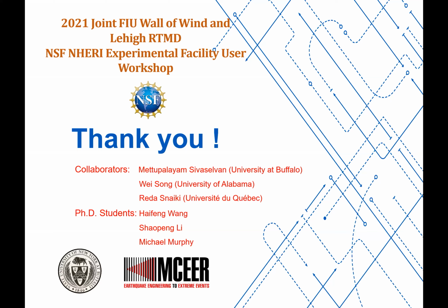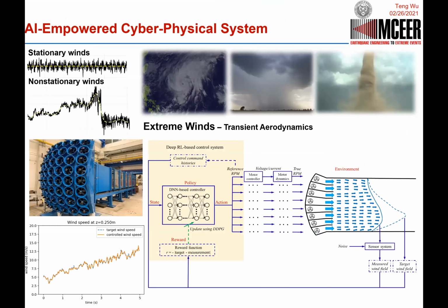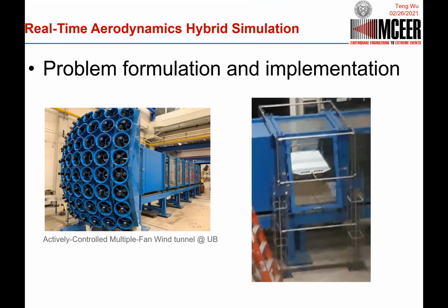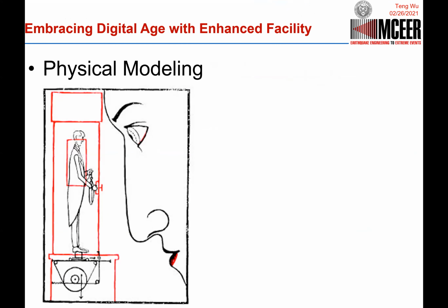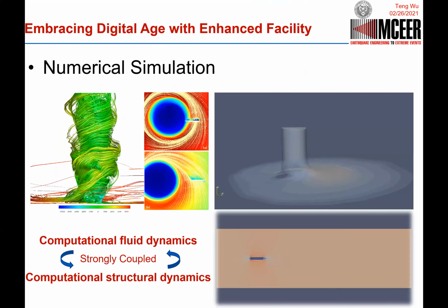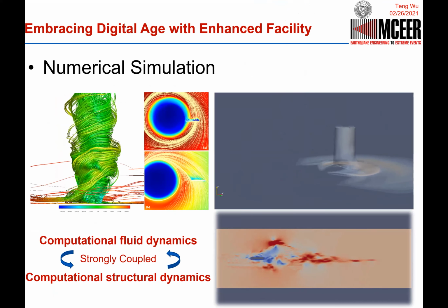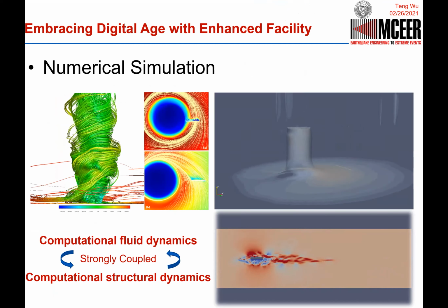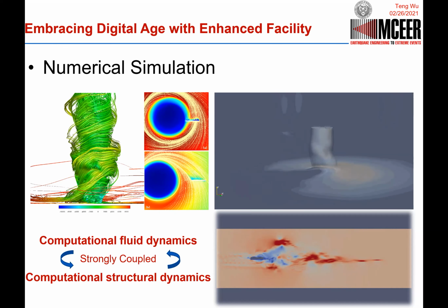Yeah, this CFD, as I mentioned, apart from the computational demand we have, the issue here is that even for CFD, you need validation. So unfortunately you still need to go to experiment, because currently in the wind energy community the full-scale data is so little. Of course, now it's more and more, but we still need to rely on the wind tunnel.